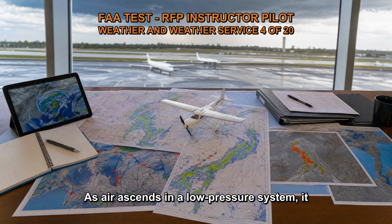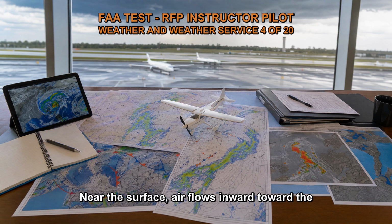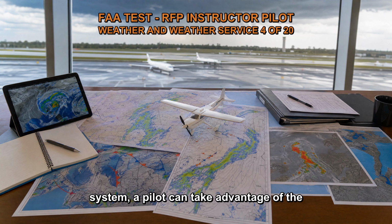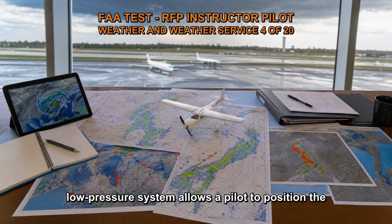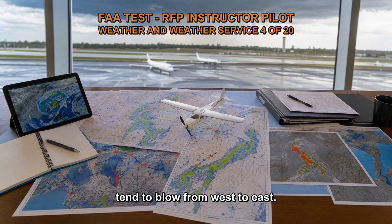As air ascends in a low-pressure system, it converges and rises, creating a region of rising motion and potential precipitation. Near the surface, air flows inward toward the low-pressure center, resulting in surface winds that generally rotate counterclockwise around the low. By flying to the north of a low-pressure system, a pilot can take advantage of the counterclockwise circulation and potentially encounter favorable tailwinds. Favorable winds. Flying to the south of a high-pressure system and to the north of a low-pressure system allows a pilot to position the aircraft in a region where the prevailing winds tend to blow from west to east.